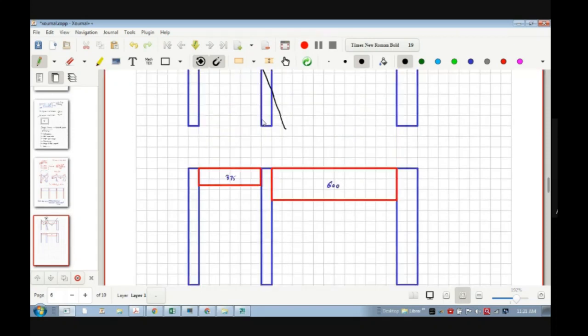Now here you will see as the beam depth is more over here, definitely the moment is more here. But this beam depth is very less, its capacity is less, so it will also have a less attraction of the moment. So ये कम attract करेगा moment. Okay. That means, let's say if it is 100, ये ऐसे कुछ तो 70 or 60 भी हो सकता है.